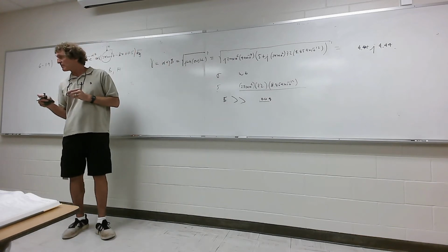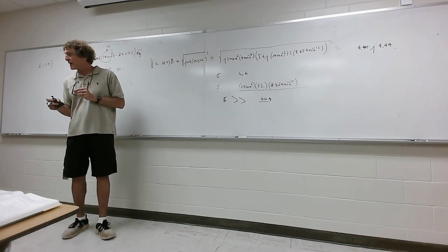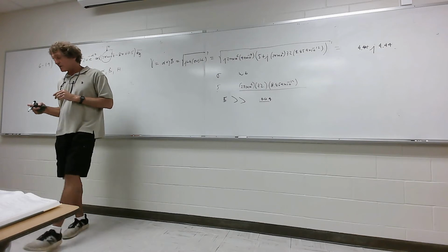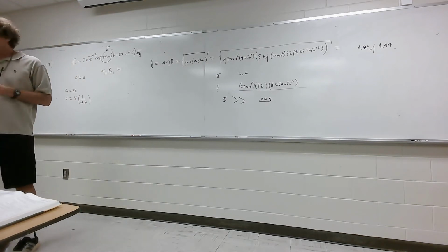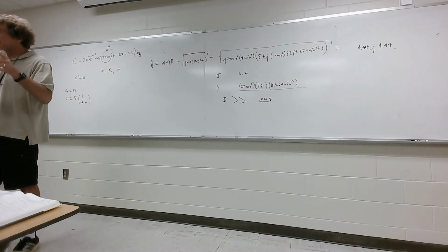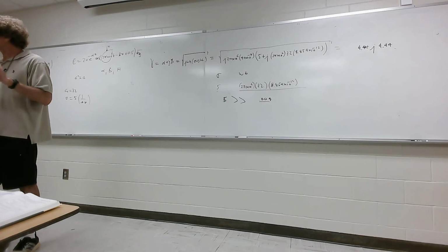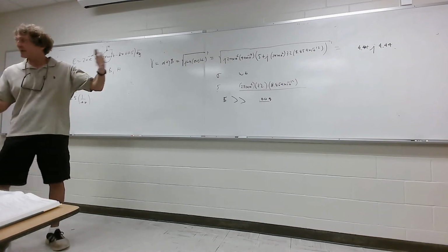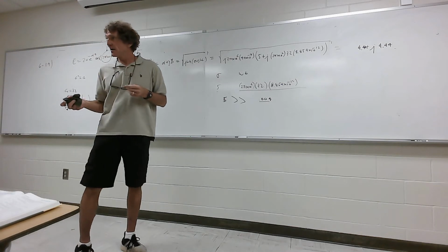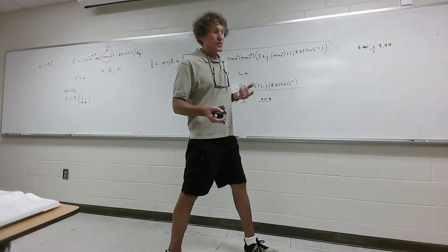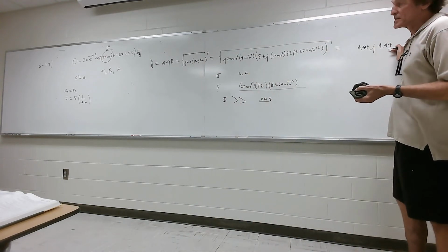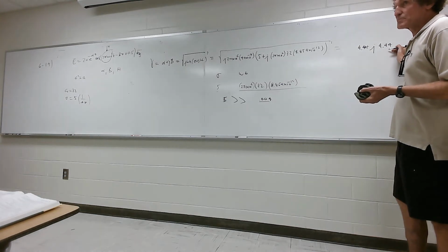What else for this one? We got alpha, beta, and instantaneous voltage. All right. What's the units for those constants? Alpha is Nepers per meter, and beta is radians per meter. But a Neper and a radian are kind of a fictitious thing. They're equated to each other. If you add them together, they have to have the same units. So it's Nepers per meter, or in this one, the beta is radians per meter. It's not degrees. Remember, it's radians per meter.